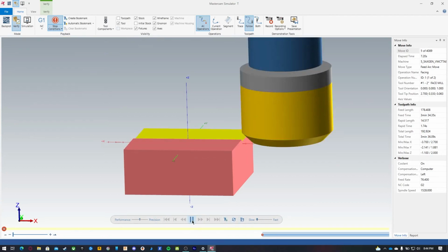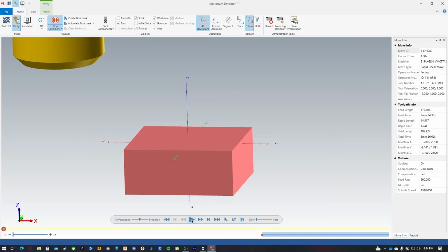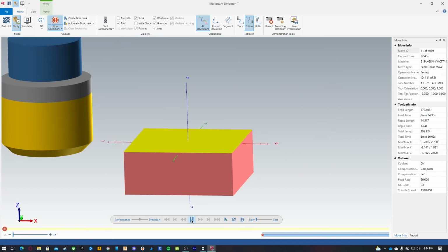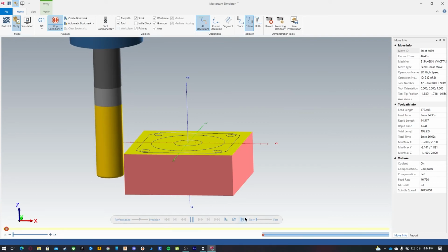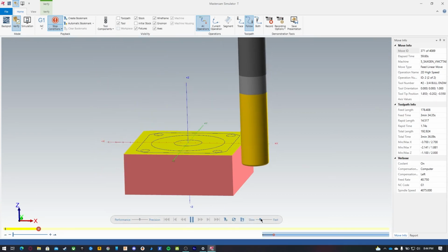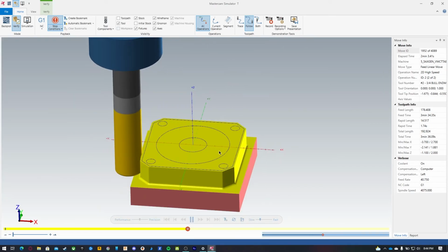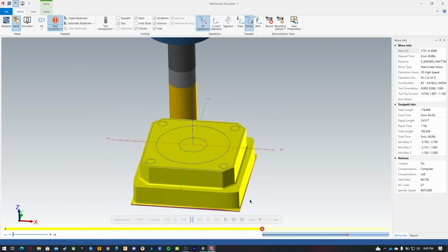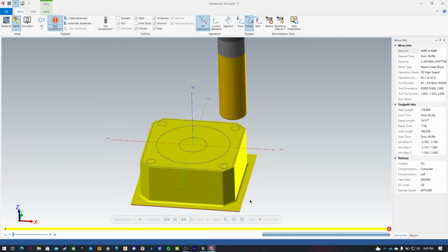So it plays, does the facing, and then it pauses for you. And you can adjust your speed slider here, so it pauses, and now we're ready to do our high-speed machining. And you can see how it did that. Keep tool down, it didn't lift up for the facing. That's what we want. So go around this part, 1 cut and then 2 cuts. So we're not holding on by a lot, so let's reduce that down.